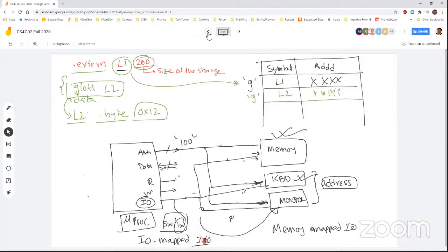Oh, okay, now I understand. So basically, back in the days, they had an extra bus, an extra wire? It's a bus bit, yes, exactly, that carries a bit of information. If it's 0, that means this is not an IO address. If it's a 1, that means it's an IO address. Then accordingly, there was intermediate electronic circuitry which resolves that access, which physical device will be accessed and read from or written into. That extra electronic circuitry is always there. All right.